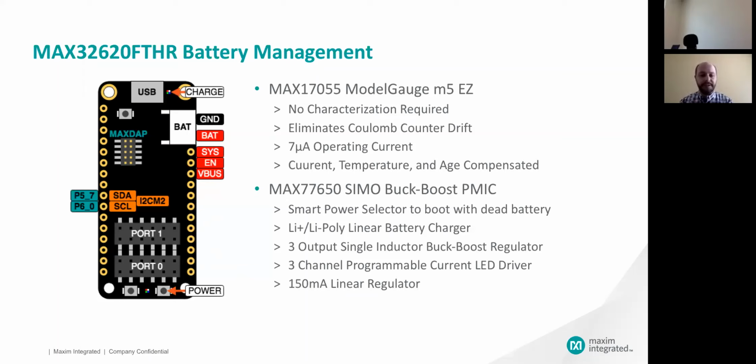The power button does turn the part on, but after the part's on, the PMIC will monitor that, and it can interrupt the microcontroller to tell it that there's a button press. So you can use the power button for user input as well.